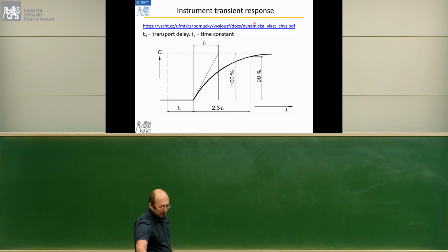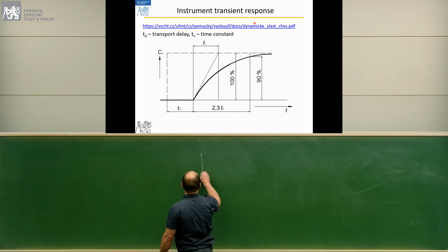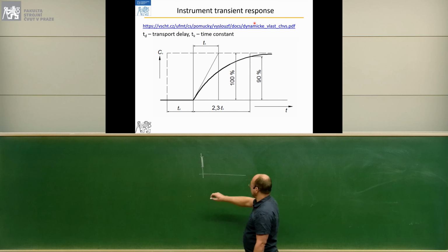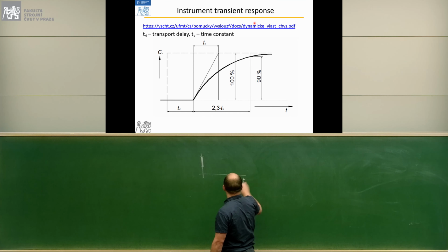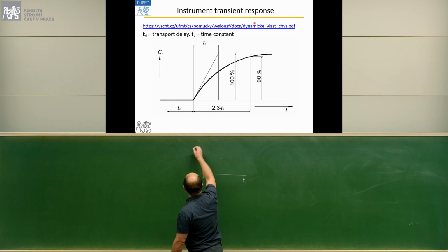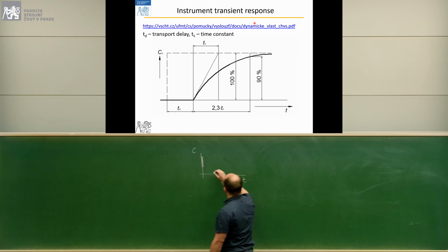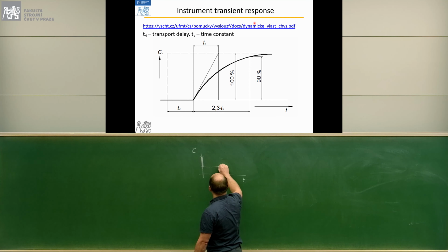I will touch on a few things about instrument response. Let's say that you introduce a step change in concentration from here to here at some time 0. And this is the instrument signal, the concentration reported by the instrument. For some time, nothing happens.